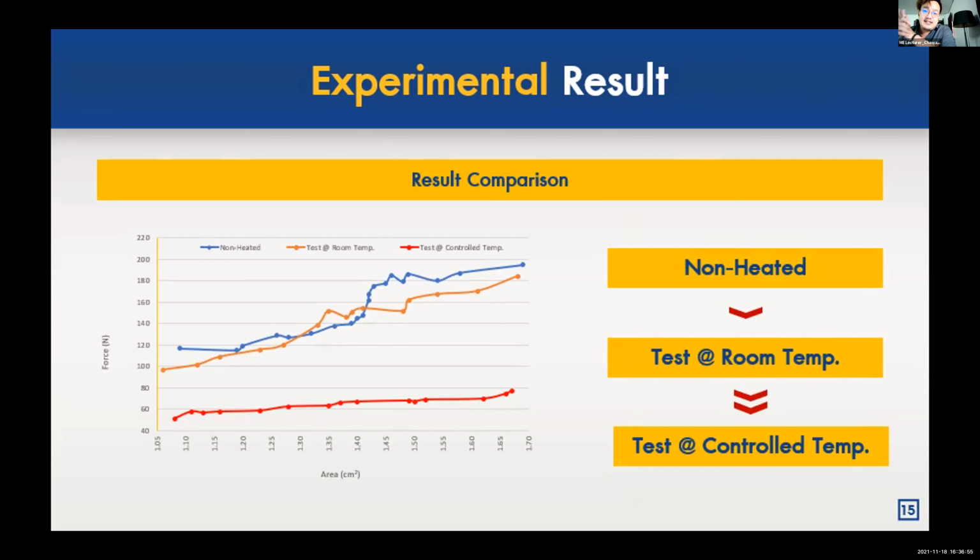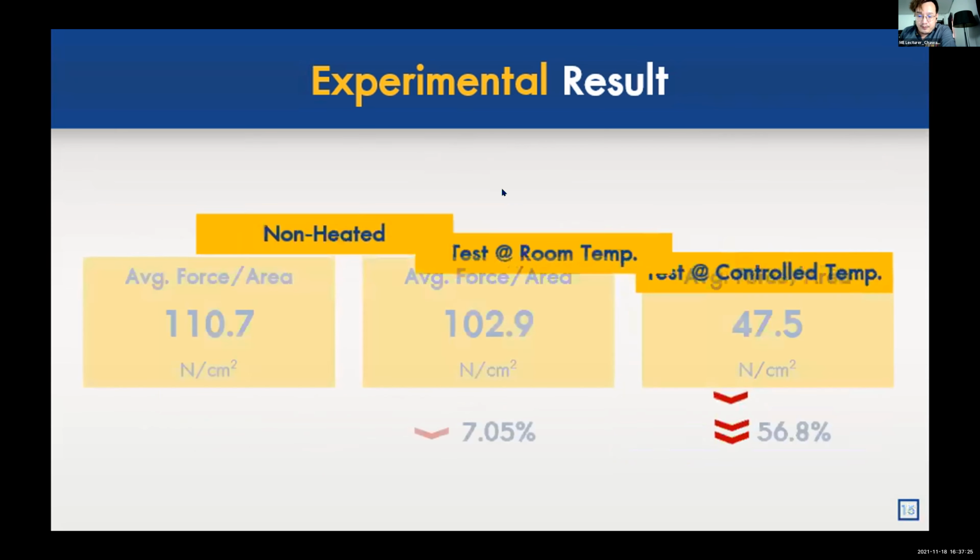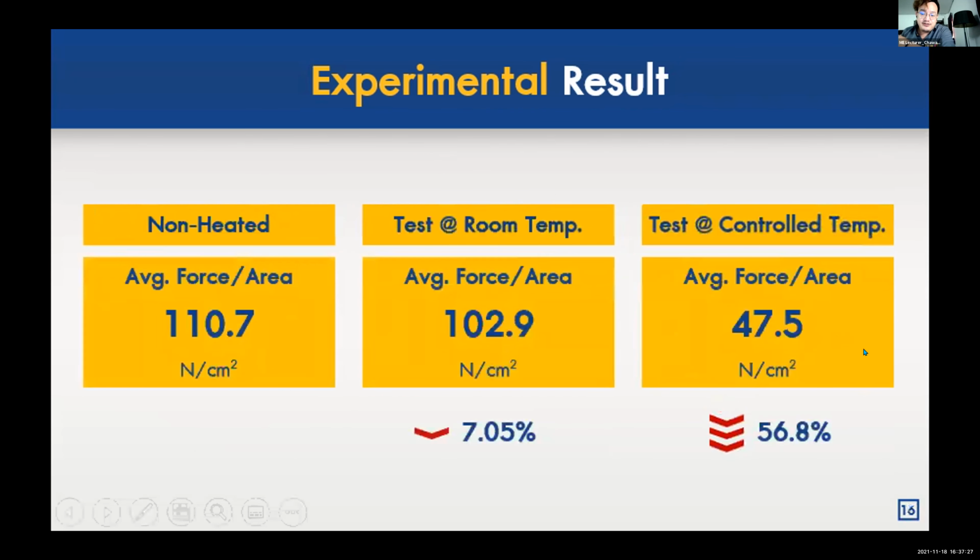After the demonstration, the process of separating the broken glass from the PV panel is easier. We checked the state of the EVA, and we found out that with the heating of the microwave frequency, they didn't lose anything in the EVA layers. So we can reduce the force by about 60% right now.